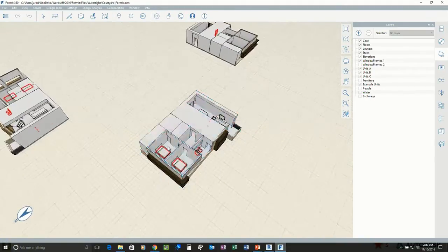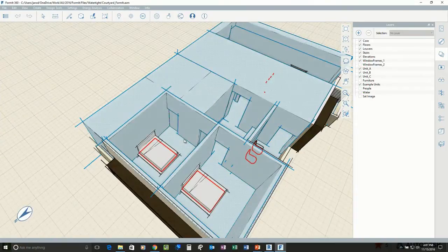So like this bed here, at some point was maybe a SketchUp model that came in, and that's something that we might have to address. If this is something that's going to be converted and brought in to Revit, we might need to work on that. So there's something with that surface where it's not watertight. At least we got something built into FormIt to show us where those issues are.